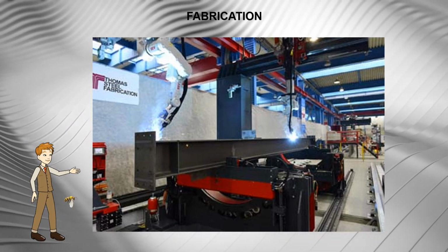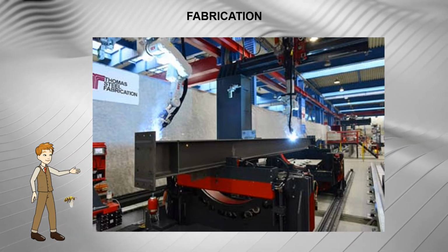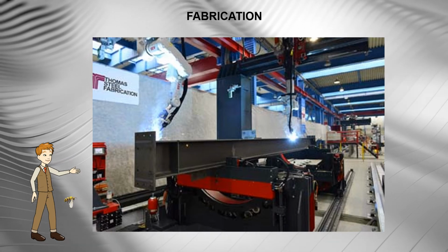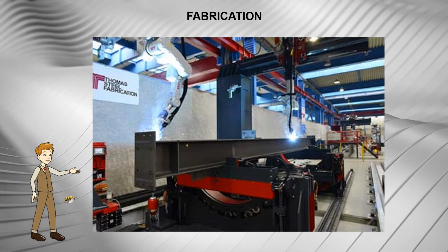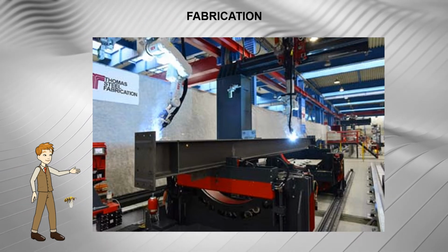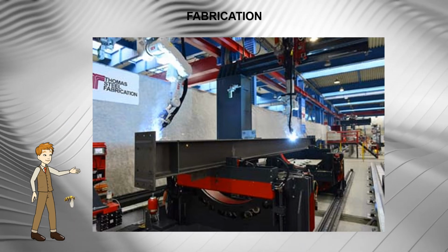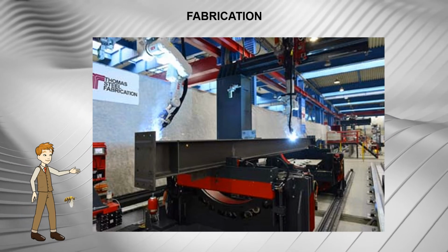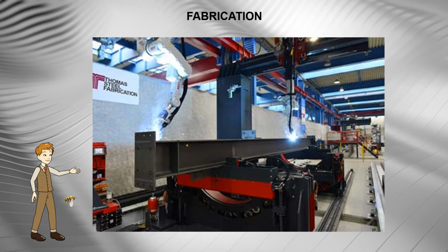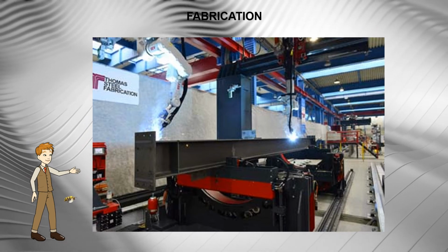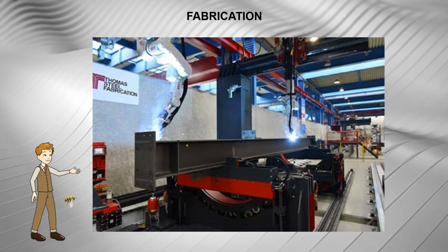The length of members available from stockists or direct from the mill can vary. When long lengths are deemed desirable, it is necessary to check their availability. Generally, standard sections can be obtained in a reasonable time, but there are likely to be delays and additional costs if non-standard sections are required. The use of slightly heavier section and standardization of section size may lead to a cheaper fabricated structure.